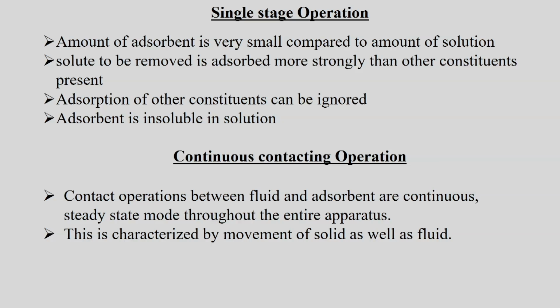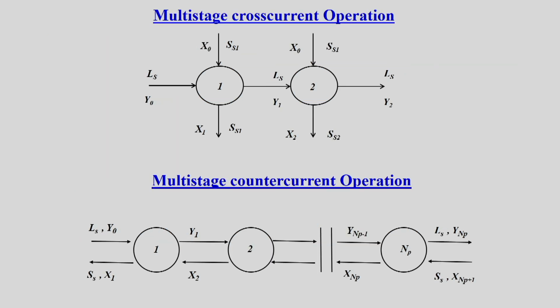For continuous contacting operation, the contact between the fluid and adsorbent is continuous, in steady state mode throughout the entire apparatus, and is characterized by movement of the solid as well as the fluid. And the multi-stage cross-current operation is similar to what we discussed in extraction and leaching. Multi-stage counter-current operation is also equivalent to what we have already discussed in leaching and extraction.